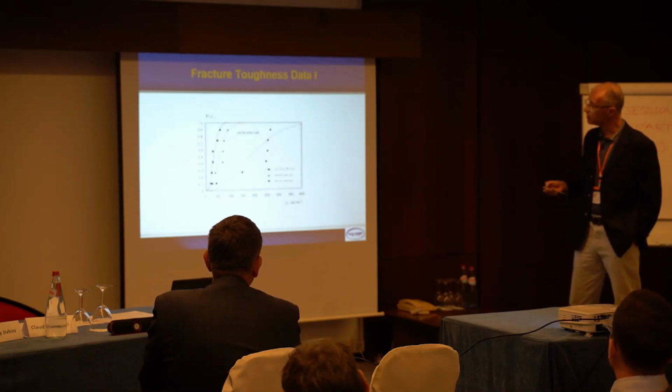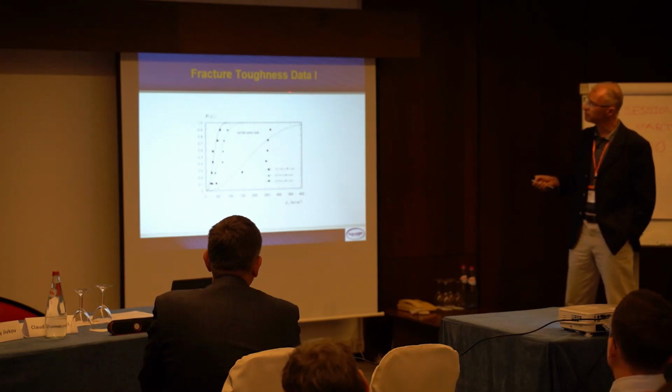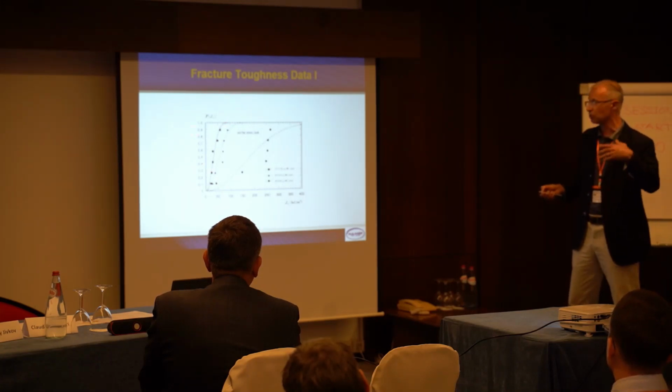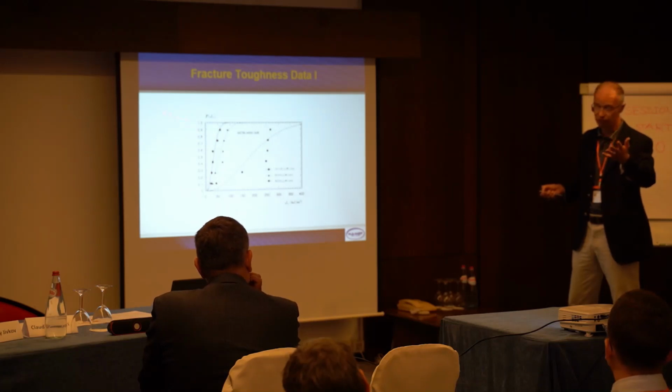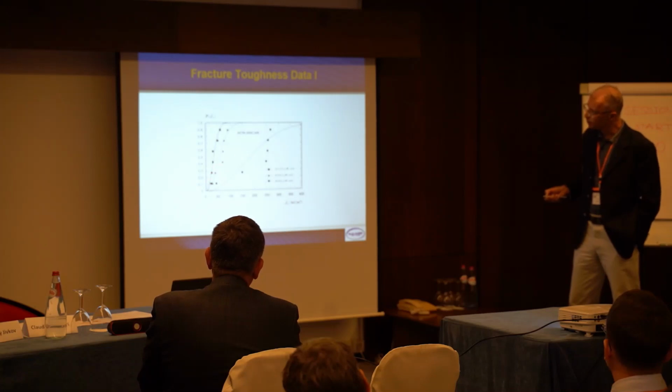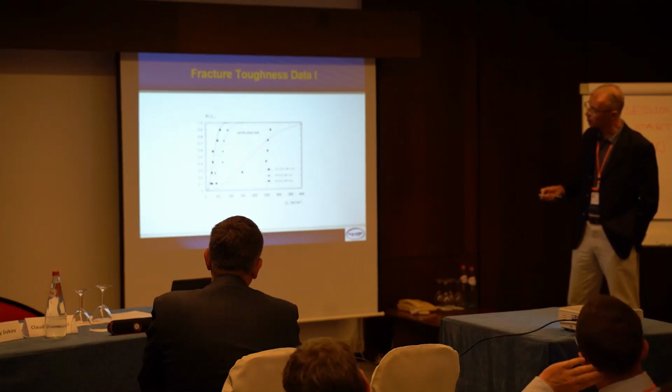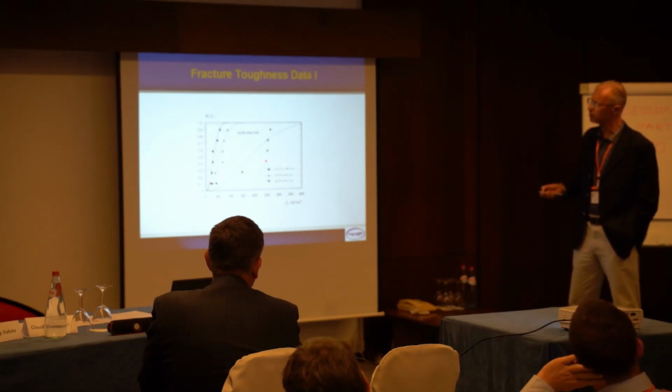Okay, these are the Weibull distributions for the data. First, you can see here the CT specimen, 1T, 1 inch or 25 millimeter thick, a/W of 0.5. This is the standard pre-cracked Charpy, a/W of 0.5. And these are shallow-cracked pre-cracked Charpy specimens. You can see here that the scatter does not fit quite well a Weibull distribution, but the most important parameter is, let's say, the J0 in the Weibull distribution.